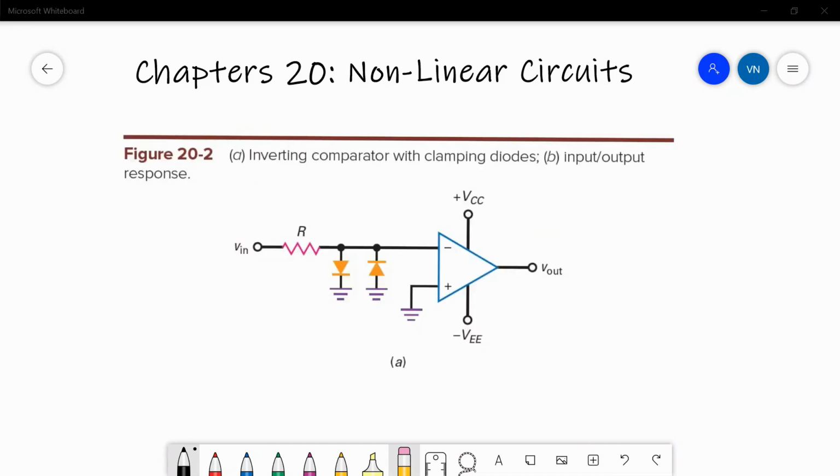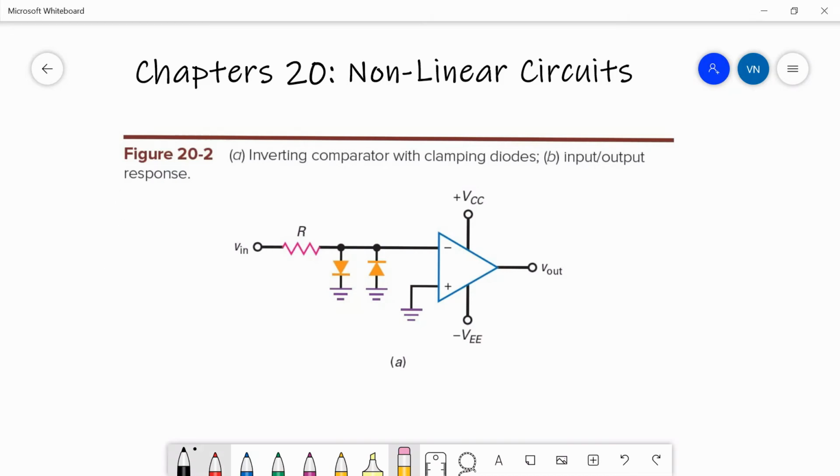So here's an example circuit of how we could use a comparator. This looks like a zero crossing detector. If you're using the 60 hertz sine wave coming out of the wall to do some timing, you could take that 120 volt signal, and if you had a large resistor like 100k ohm to keep the current down, you could put that into a couple of diodes.